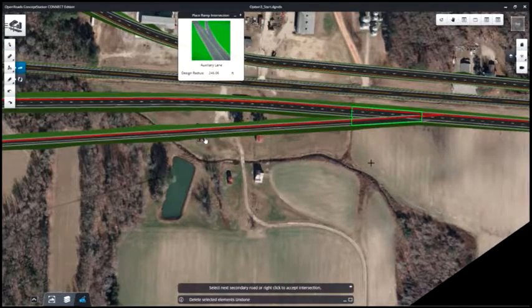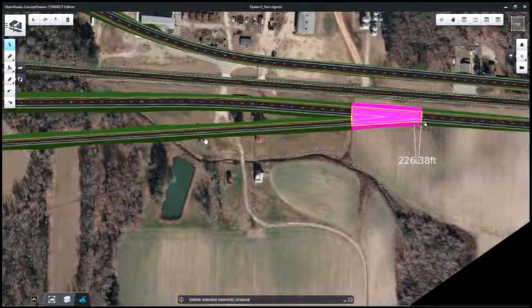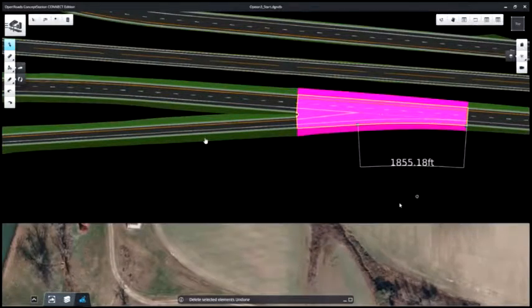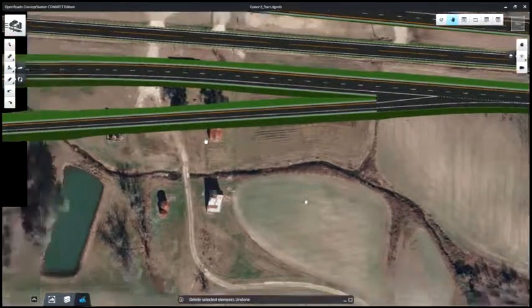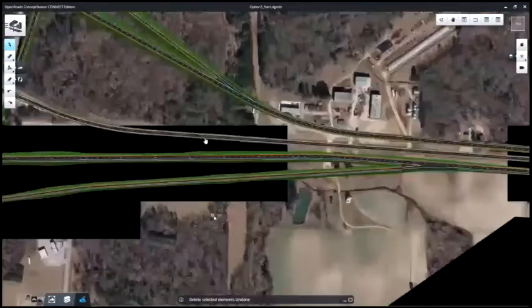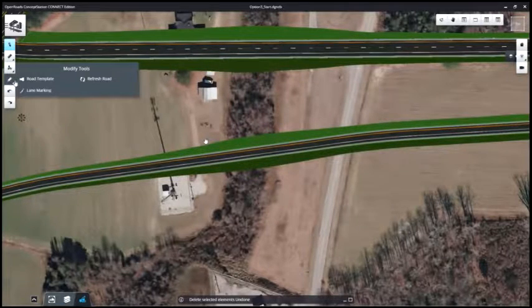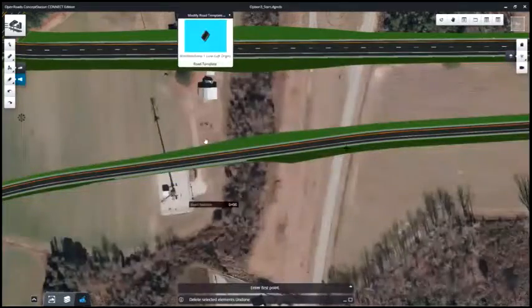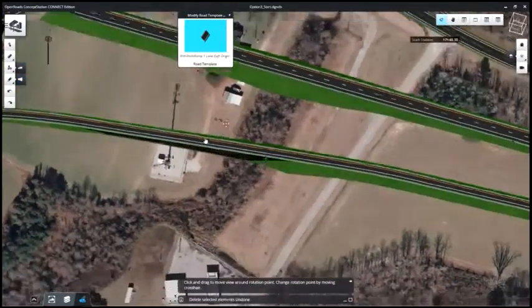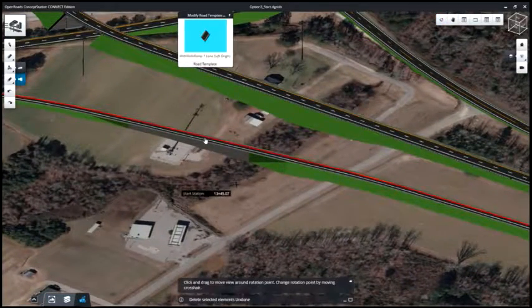Another example is the intersection tool. With the intersection tool, you can join two pieces of roadway, and then by just simply using the intersection tool at that intersection or that proposed intersection, it automatically will do a best fit based on design standards. So the key here with Concept Station is the ability to model quickly by using the best practices, if you will. Now, you have the ability to override things as well, maybe not to the level you would in a detailed design package, but the idea is to basically go with the best fit at all times. That way, most of these tools can work very simply with just a couple of simple clicks.